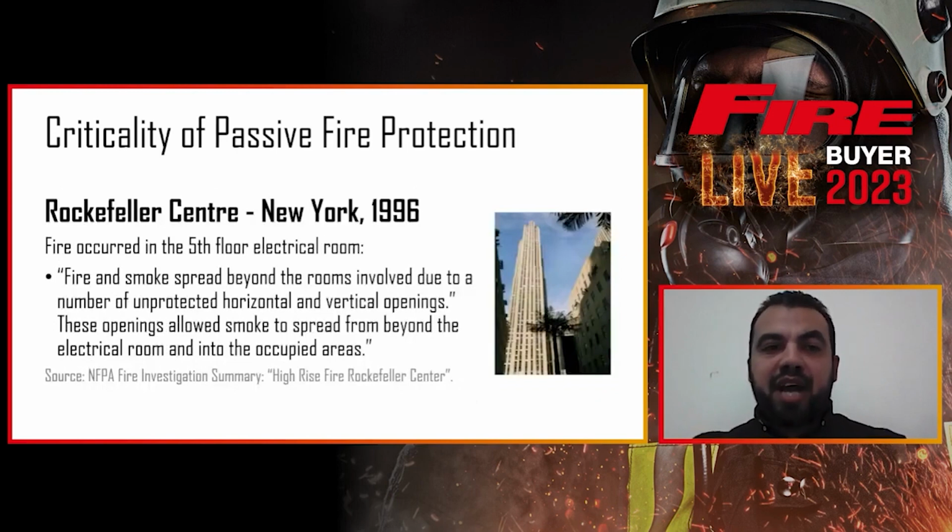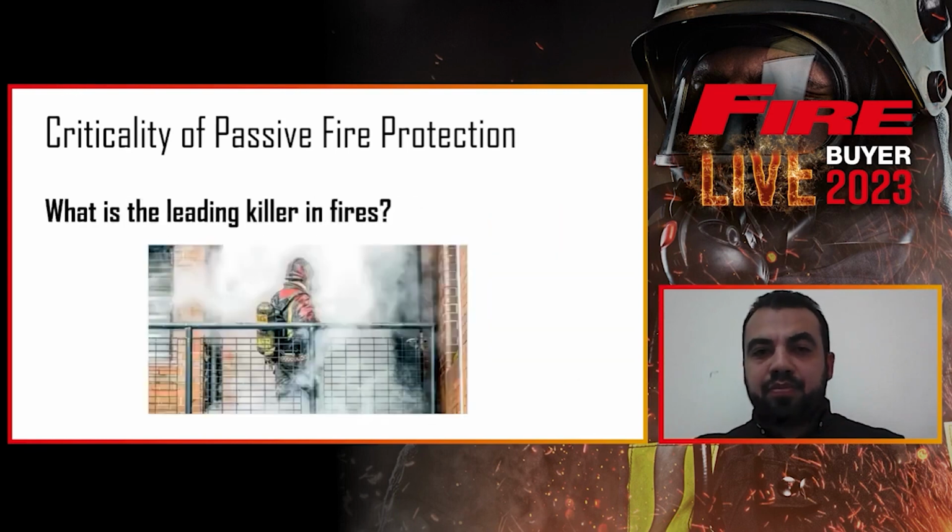Another fire happened at Rockefeller Center, and the main cause of fire spreading was no fire stopping or bad fire stopping of the horizontal and vertical openings.